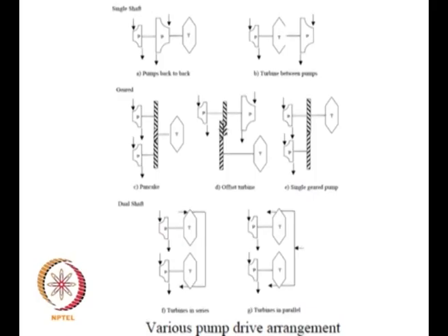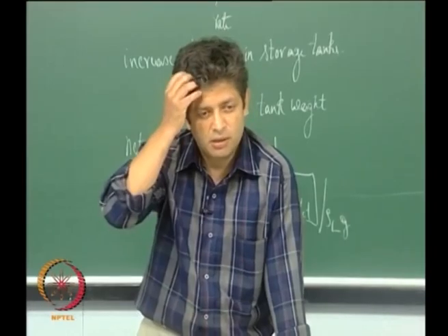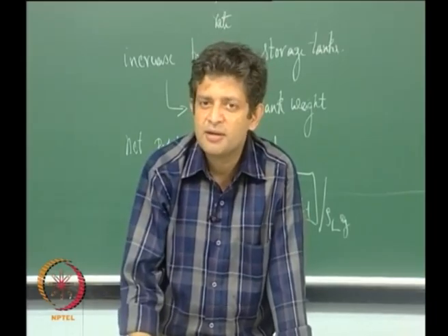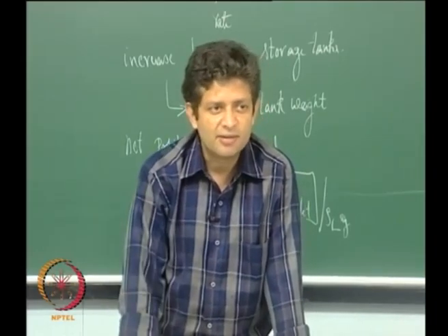This kind of arrangement has been used in the space shuttle main engine, and this kind of arrangement was used in the F1 engine, okay, the F1 engine on Saturn that took man to the moon had this kind of arrangement for LOX kerosene, okay, wherein densities are similar. That is, if you look at LOX, liquid oxygen is around 1100, the other one is around 800, okay.